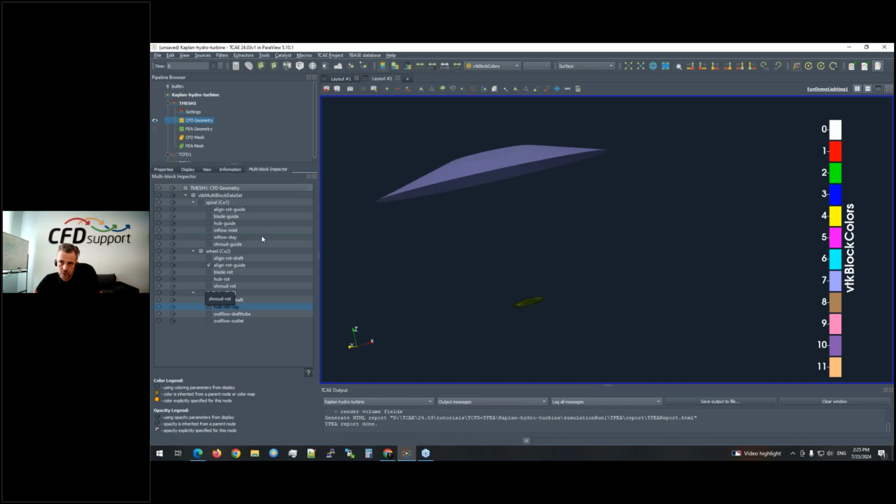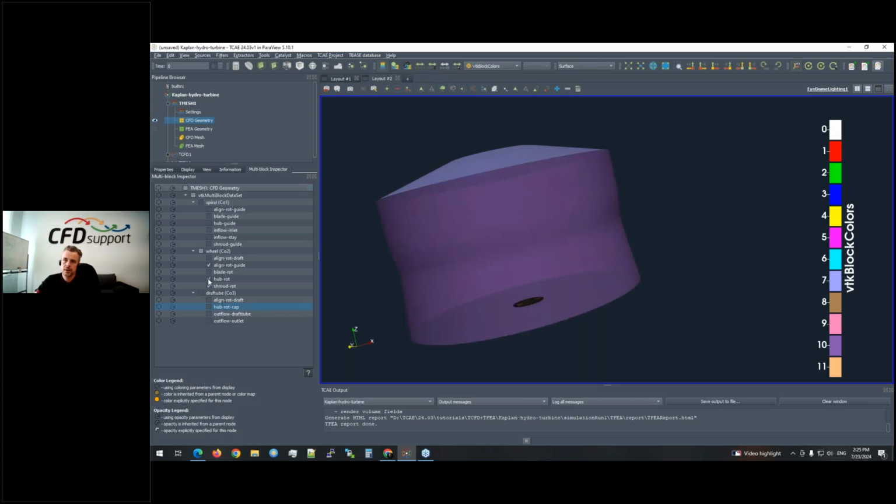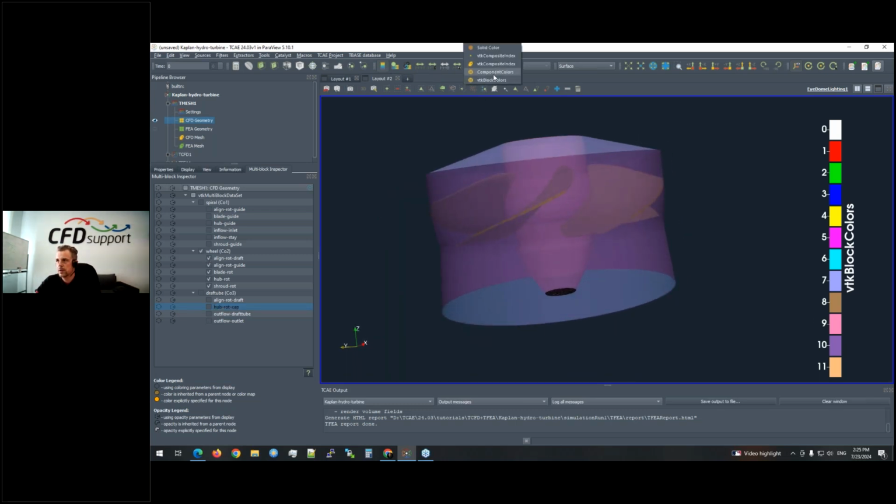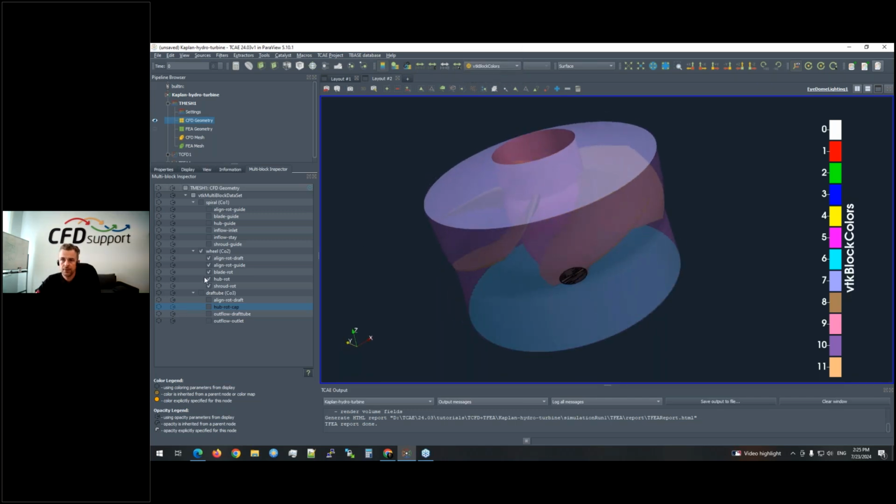So it allows the use of advanced methods like mesh refinement and also the evaluation of the results in post-processing. But those are perhaps too detailed for this webinar. So I will go ahead with this information: you have to have watertight components, the interfaces should match, and that is good enough to get quite good results.